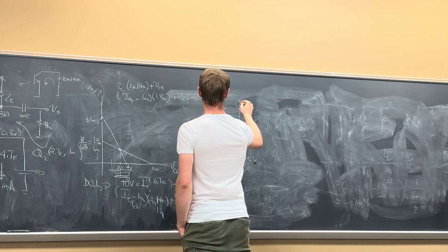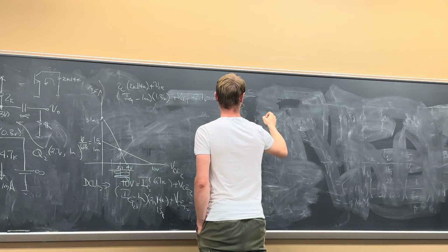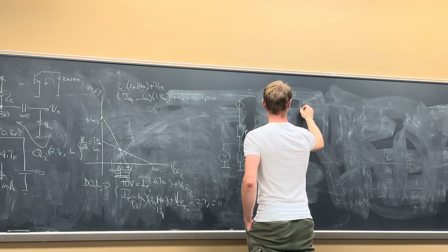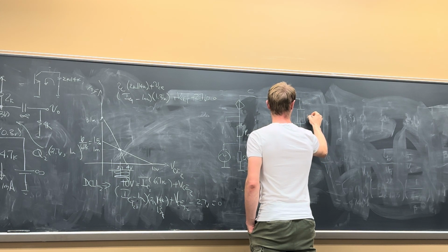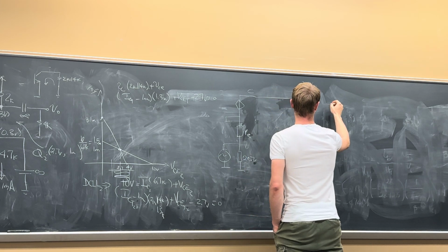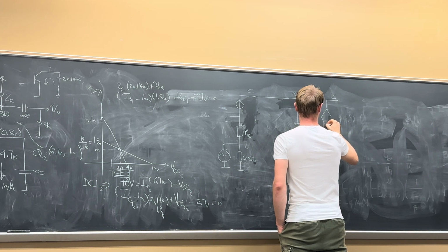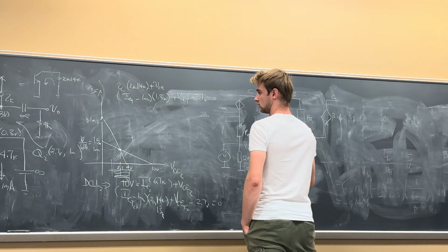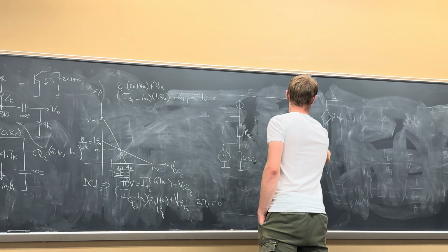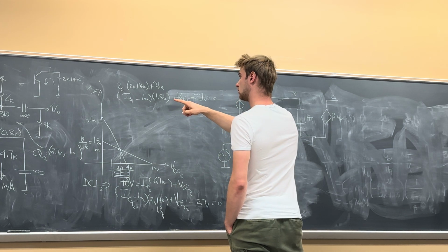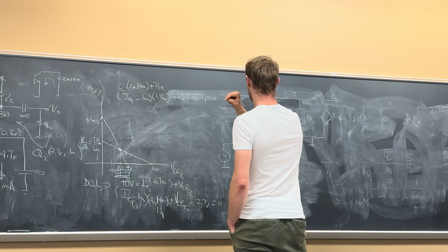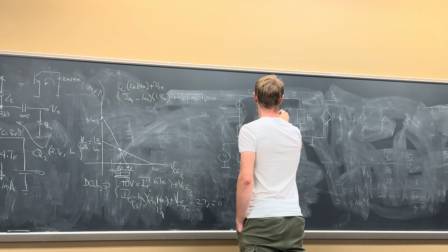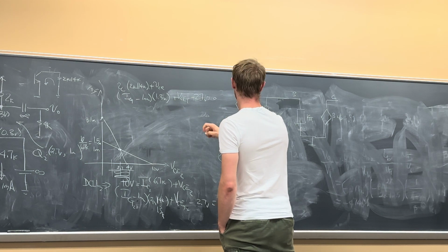All right. The collector goes into the second stage. That's a ground. And then you have the 2K on the front between the two, right there in the first circuit. You have 2K on the collector, you have 2K, that's the load, right? On the output, you have the 2K in parallel with 4K, 1.3K, right?